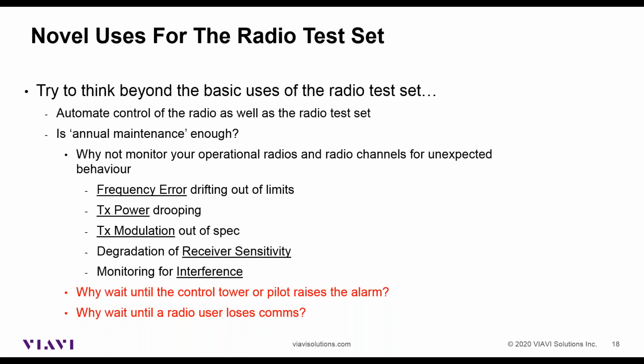An animal walks past at night, the spotlights come on, it triggers an alarm, and the receiver gets compromised because of the broadband noise from these, in some cases poor quality, LED lighting inverters. LED light bulbs at home also cause a similar problem. So if anyone's having problems around dusk, or they suddenly see problems in the evening and at night that don't happen in the daytime, it could well be LED light bulbs.